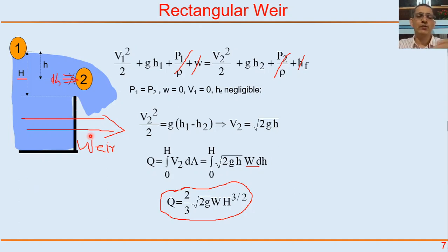So civil engineers or environmental engineers, when they want to measure the flow rates in large streams, say wastewater, or storm water flows or river flows, you can put a weir in that and measure the height. So whenever, let's say, a bridge is being built, it partly blocks the cross section of the river. Let's say we are trying to build a bridge on a river, so the pillars of that bridge block partly the flow of that river, and same thing happens, that the flow happens over that weir or over that blocked portion.